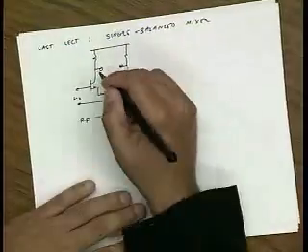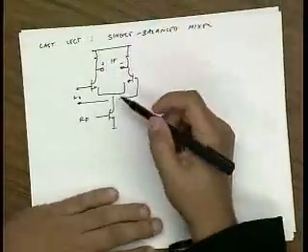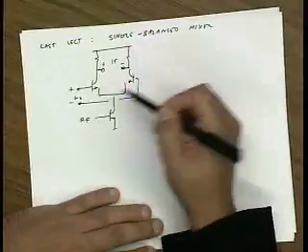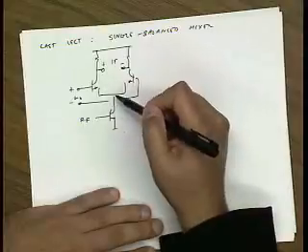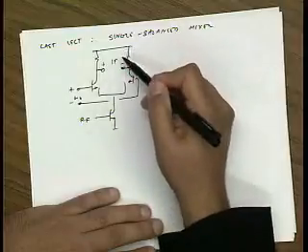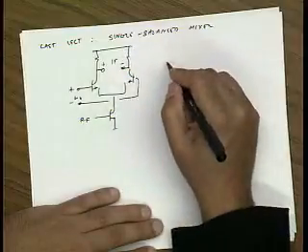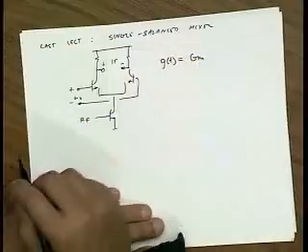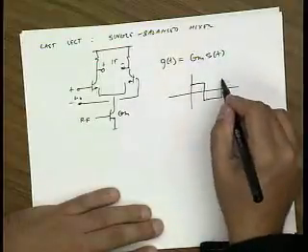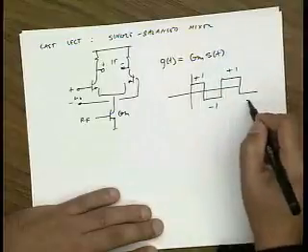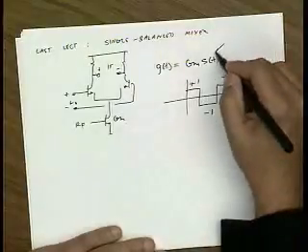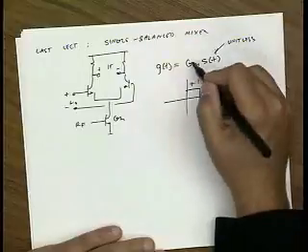Okay? Now, because the output is taken differentially, the circuit operates just as before. We swing our current either to the left or to the right, depending on the magnitude of the LO. If we swing it left, this side is positive, this side goes negative. If we swing it right, the opposite happens. It looks like now we're multiplying our constant GM of this device by an S of t, which goes between plus and minus 1. S of t is unitless, and this is a regular GM.